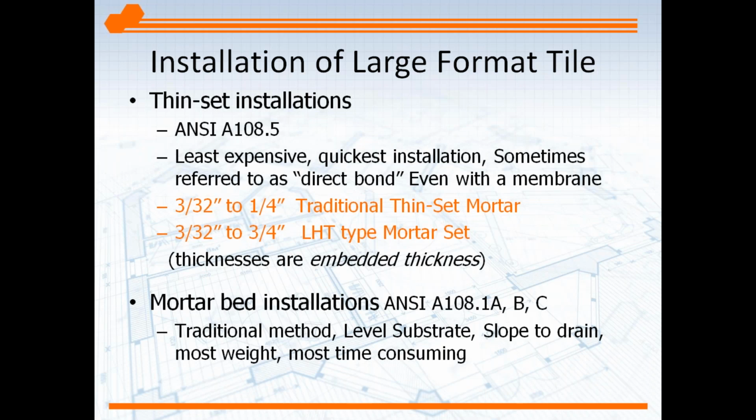In order to do that with a large format tile, traditional thin set mortar could not go in deep enough. You can see on the drawing here, on the slide in orange, 3/32 to 1/4 of an inch deep with traditional thin set. That just wasn't enough for a large format tile. So what was happening is tile installers in the beginning were taking that traditional thin set and they were putting it in thicker, deeper, to accommodate for the lippage, to be able to push that tile down.